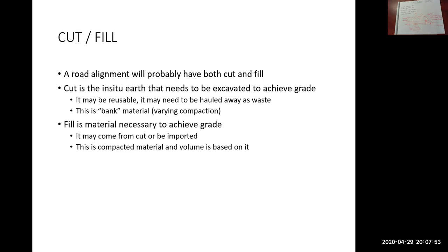If you're backfilling something that is never going to be driven on, maybe you don't have to compact it with a compactor. Maybe it's just the backside of the bucket of the excavator. So as you dump it in, you kind of push on that filled material with the back of the bucket. It's called a bucket pack.